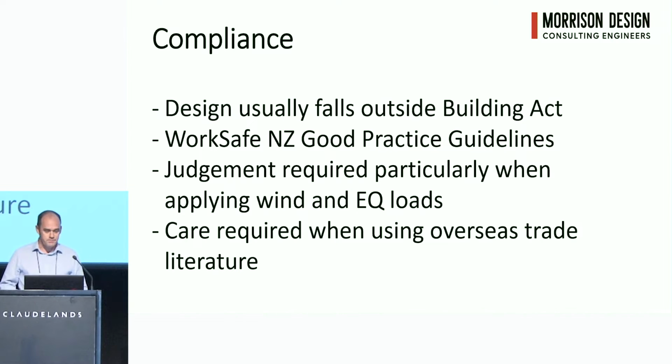A lot of the trade literature and products for scaffolds are designed overseas. They're intended for the overseas markets. So we need to have care when we're applying these overseas products to the New Zealand situation. And often that will mean down-rating the published data for the products we're using in order to comply with the WorkSafe requirements.